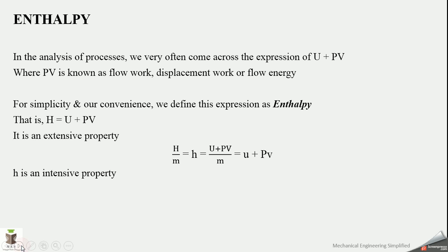Okay, let us begin. First of all, we need to know what is a term that is known as enthalpy. We very often come up with this term in the analysis of processes in thermodynamics. And what is that? We will see. During the analysis of a process, we very often come across the expression U plus PV, where U is the internal energy and PV is the flow work or displacement work or flow energy. So for simplicity and convenience, we define this expression as enthalpy.